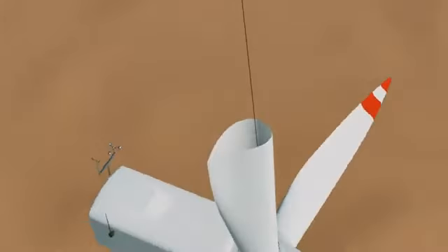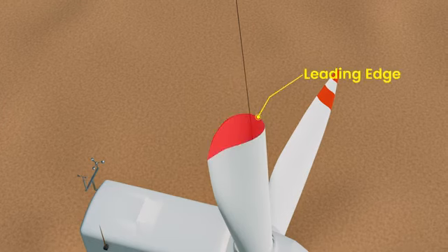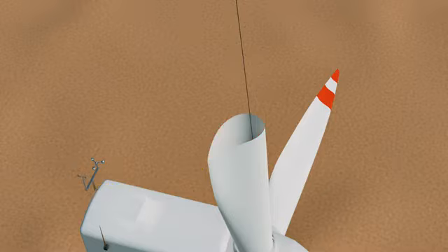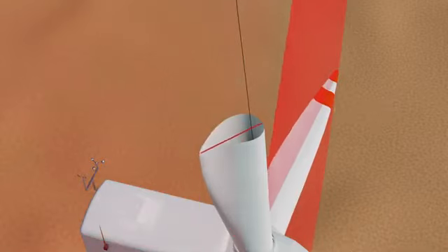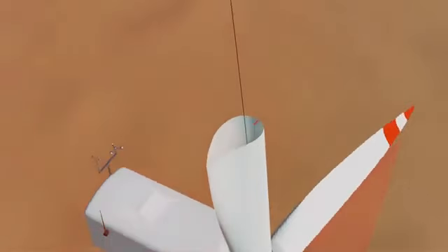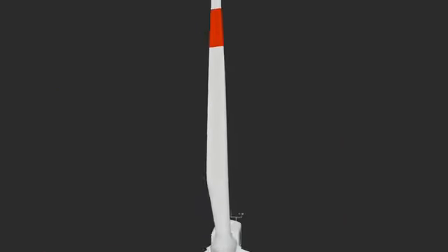The leading edge is the front edge that encounters the wind first. The trailing edge is the rear edge where airflow leaves the blade surface. The chord is the straight line distance between the leading and trailing edges. The pitch angle is the angle of the blade relative to the plane of rotation, which is adjustable to control power output. The rotor blade is thick and very wide at the root, tapering to be thin and narrow at the tip.